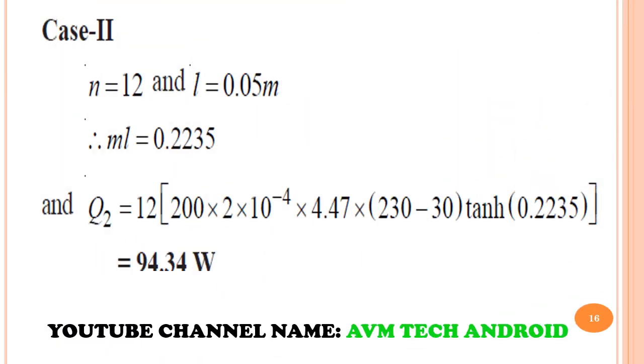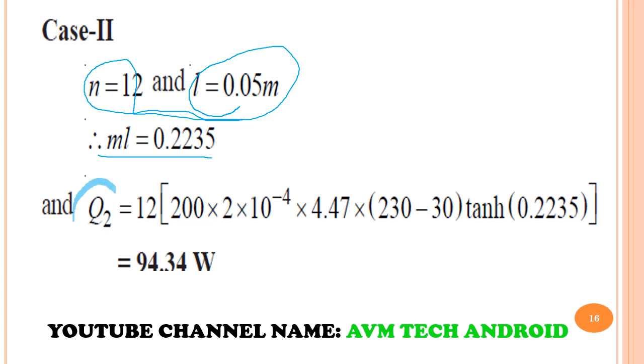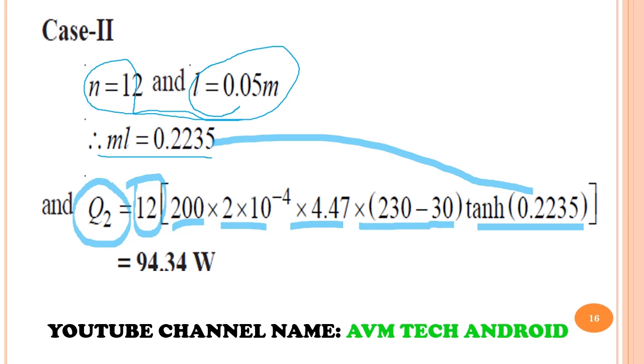Let us go for the second case where we will go for 12 number of fins. You can see length of fin is 0.05 meter. So M into L value is calculated, and that value is, you can see, 0.2235. So now we want to know what is the Q2 value. So here 12 number of fins into area, thermal conductivity, M value, T0 minus TA, tanh ML. So this ML value we have to put here. So for second case we will get the heat loss is 94.34 watt.